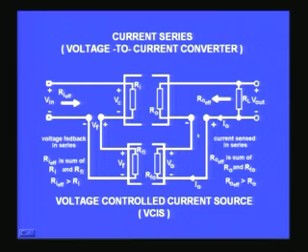So the effect of connecting something in series at the output is to increase the total resistance. Now it is R0 plus RF0, and therefore the effect is to increase the output resistance from this side, and the effect of giving a voltage in series with the input is basically again to increase the input resistance. So the input resistance is also increased, the output resistance is also increased by this feedback configuration.